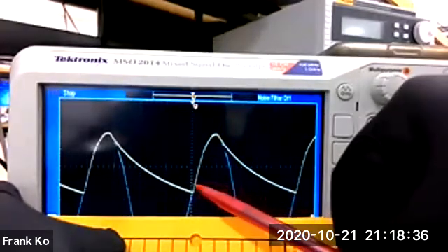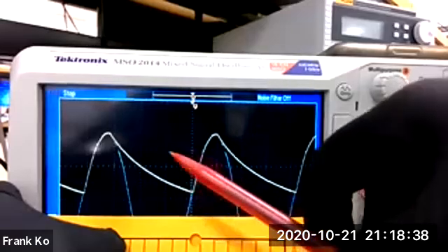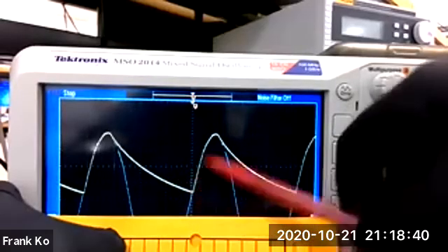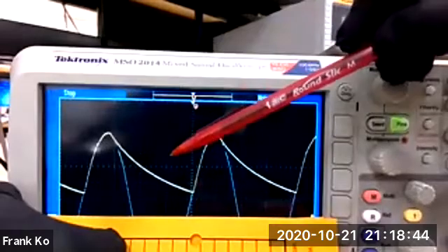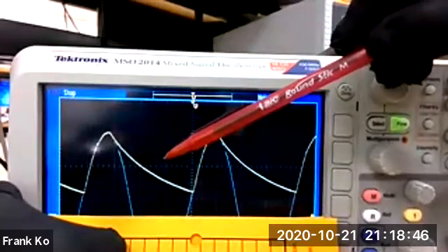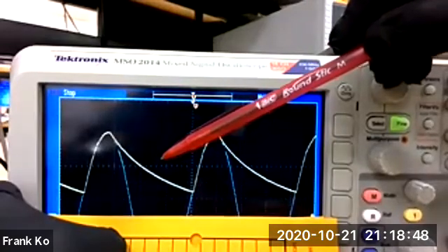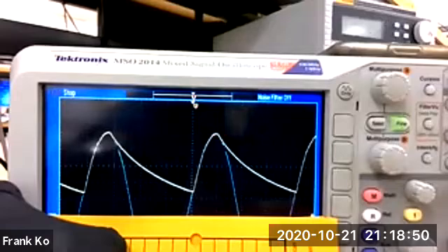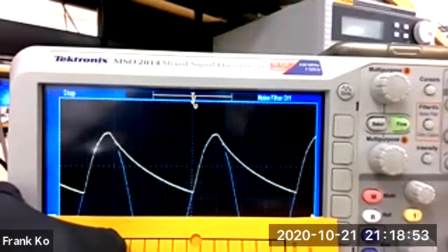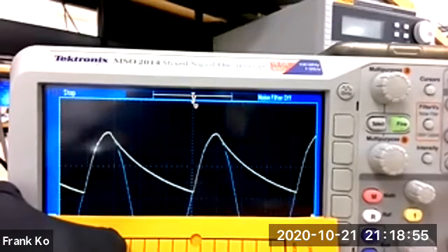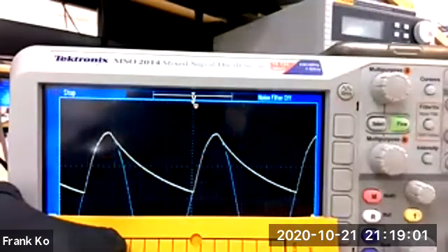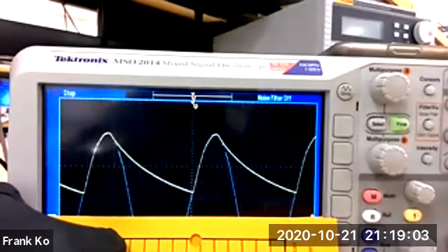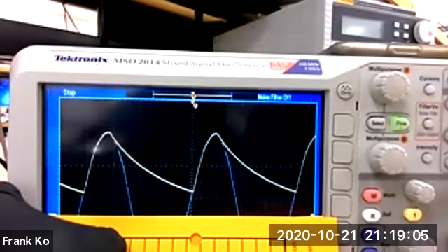And what you're going to find as we put in different size capacitors, this amount of ripple will become less and less. Has the capacitor done its job? What's the job of the filter capacitor? What does it say in the big picture of the power supply? What's the job of the filter capacitor, Ivan? What's its purpose? Smooth out the DC pulsations. Have these pulsations been smoothed out some? Yes, it has been smoothed out some.